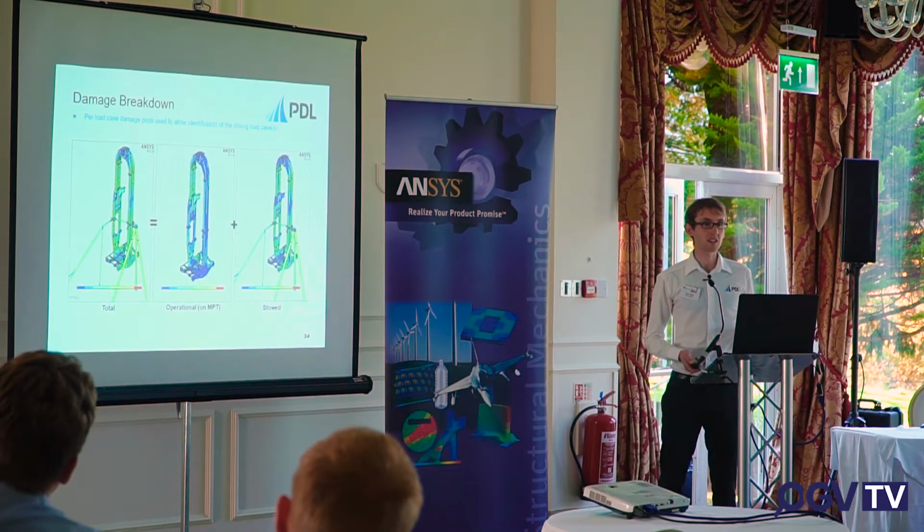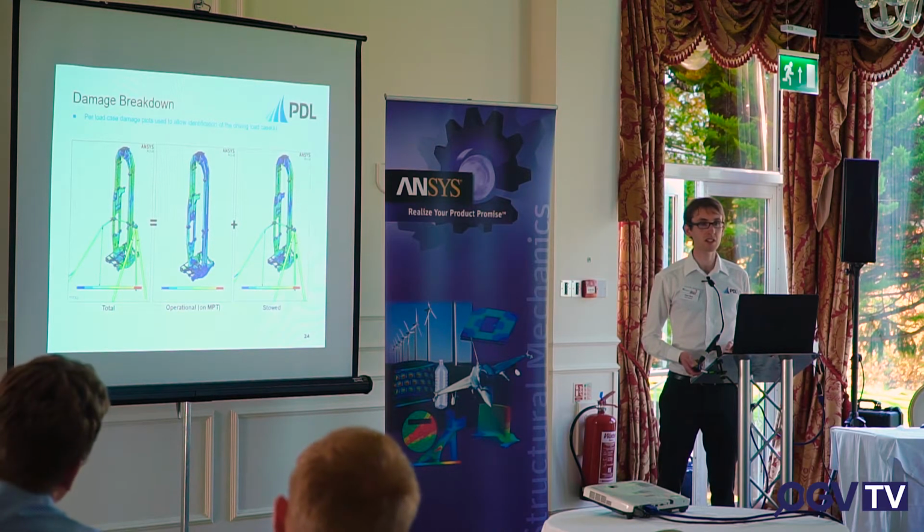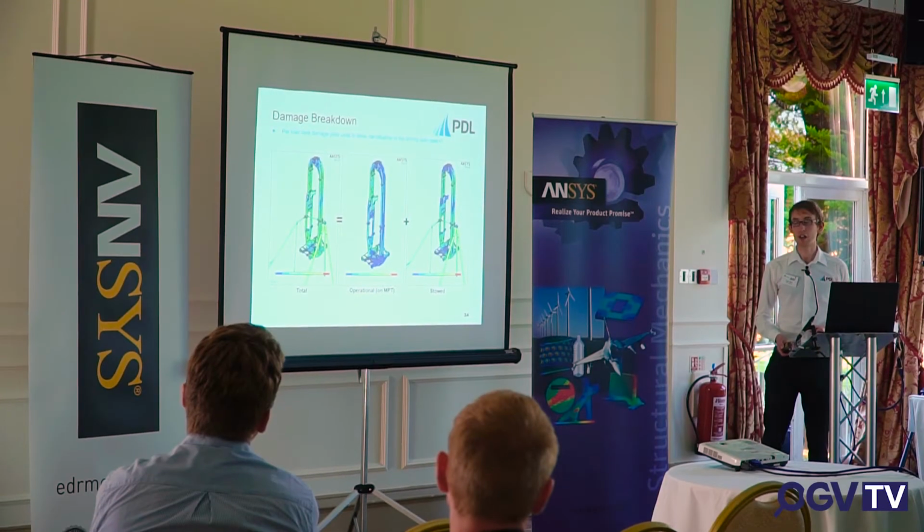But actually, it's designed to be a tension frame. It's very good at taking 500 tons in tension, hanging off the bottom of it. When it's stowed and it's sea-fastened, it's less designed to do that. You obviously can do it, but it's not its nominal operating scenario. So actually, it's more fatigue critical for it.